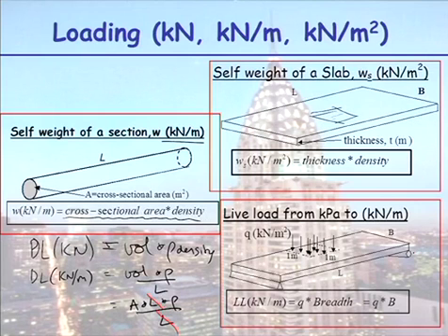So in terms of the live load as well, in the end we came up with an equation where we say, well, the live load in terms of kilonewton per metre is whatever the live load is, and when we're given a live load, we're always given it in terms of kilonewton per metre squared, how much live load acts on an area. So once again here, if you then want to work out that live load in terms of kilonewton, you would then say, well, that's my live load times my area, B times L in this case, and then when I want it in kilonewton per metre, I divide by the length. And you can see here, once again, your lengths cancel out. So the long way, not much longer, one extra line. The short way. However you understand it, you do that way.